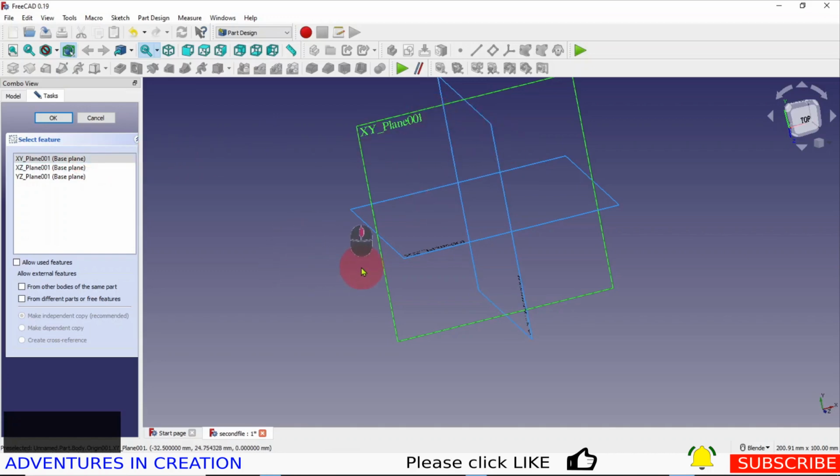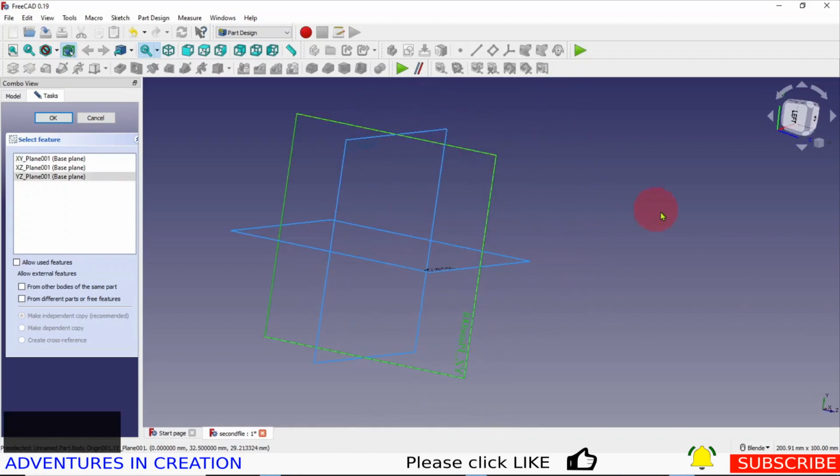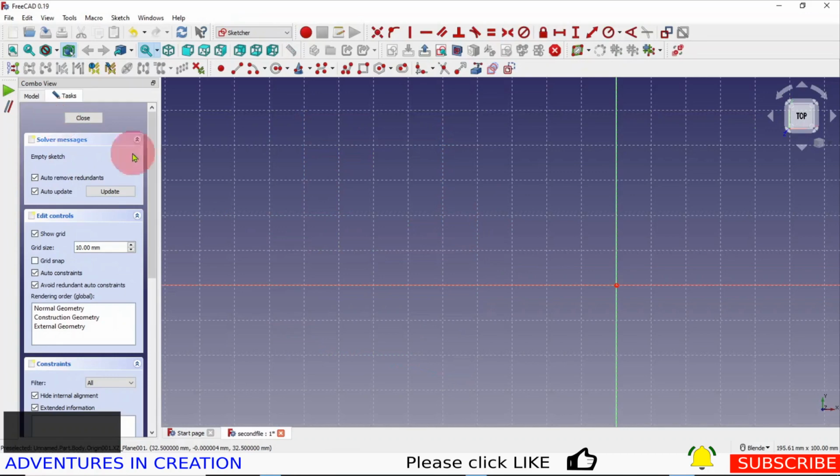So if I wanted to do it in a different plane, it's easy for me to see this plane or this plane, but I know I want it in the XY plane. So I can also select it from here, and that's what I'm going to do. I'm selecting the XY plane, and I'm going to say OK. When I do that, as I said, it switched us into the Sketcher workbench. The Sketcher workbench has all these tools in it. So these are the tools that you need for sketching.